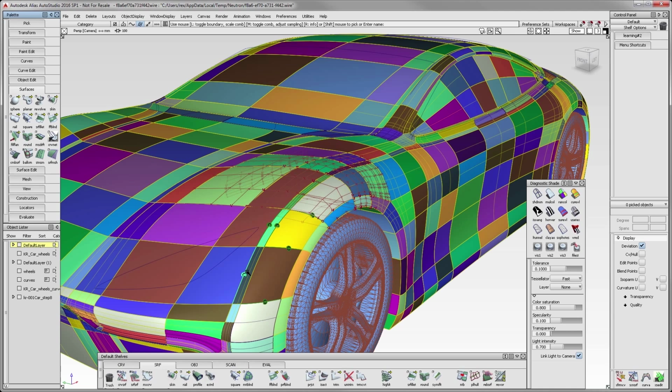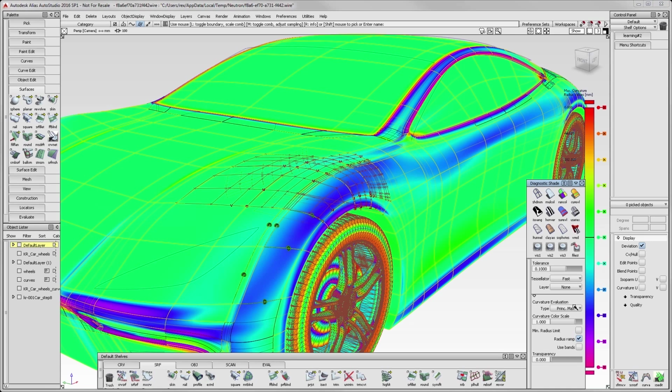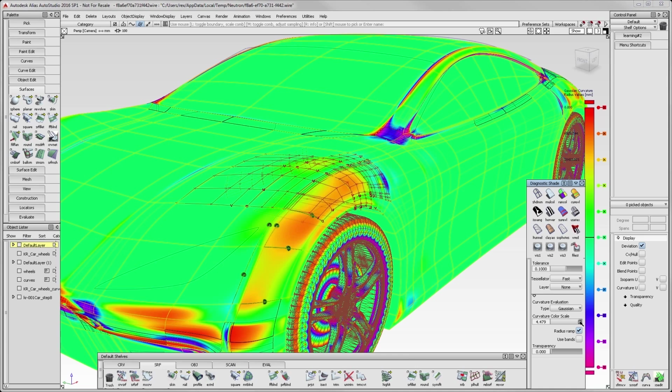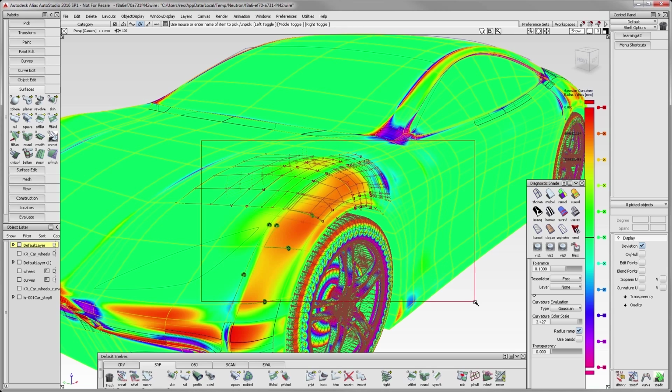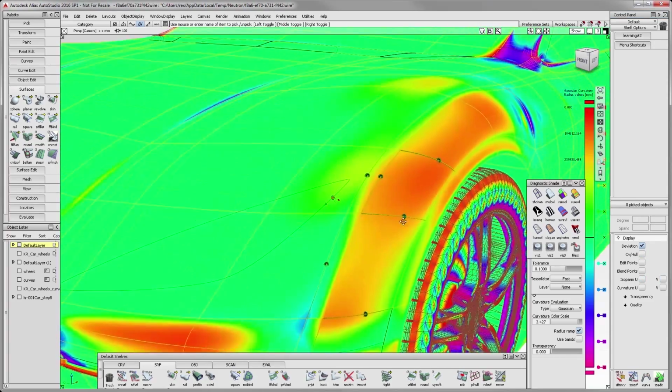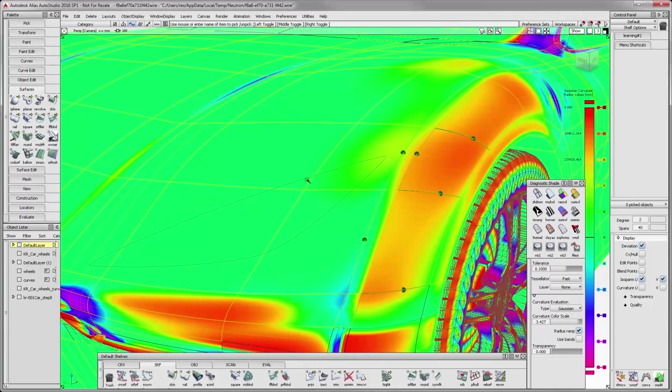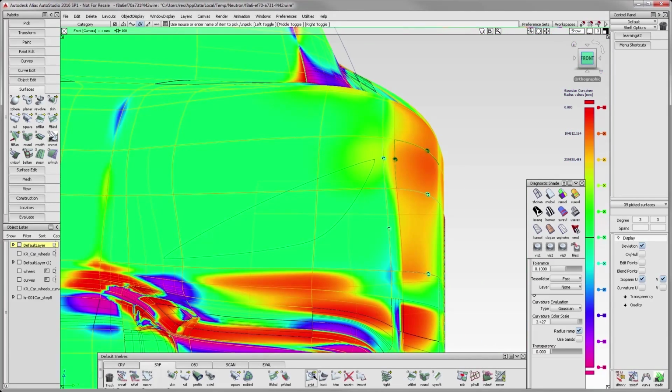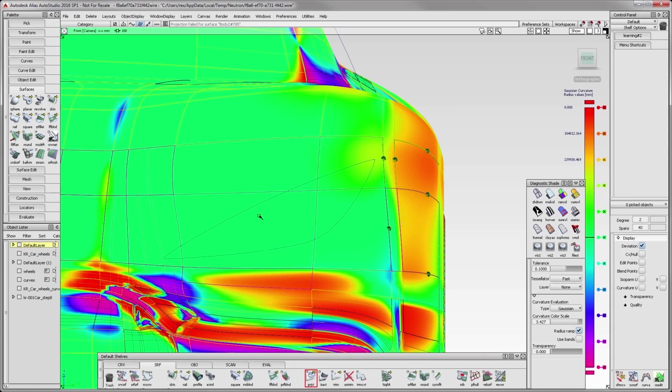Obviously, this is not a Class A surface model, but the B-spline surfaces are usable, can be extended to make a more reasonable patch layout, or used as a direct reference for rebuild. This can be significantly easier than having to rebuild a model like you would with a mesh modeler. You should also notice that the Speedform curves are included in the transfer process. In this case, I'll use the curves to project to the front surfaces.